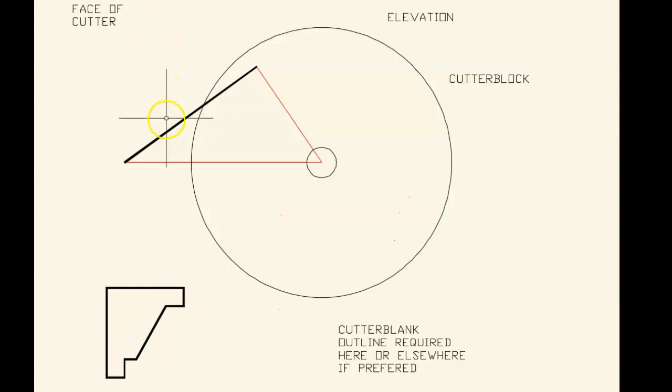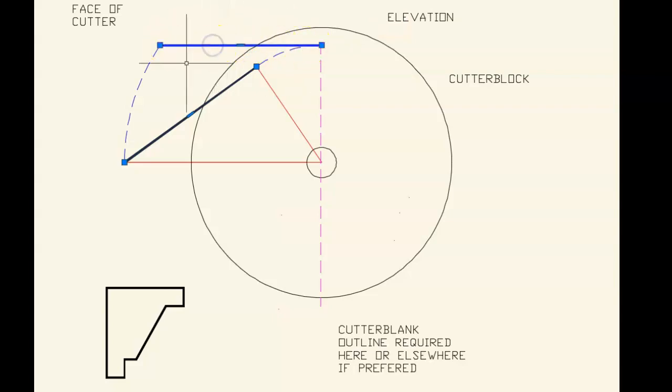Okay, so in order to start off, what we have to do is rotate this blade so that it's parallel to this molding. So to get its position in parallel, we draw a construction line from the center point of our spindle, and that's rotated around here, and then we can take this line from the center of our spindle upwards, and that's the position of our blade. And you'll notice that this line here is the same as this line here, just rotated around, that's all.